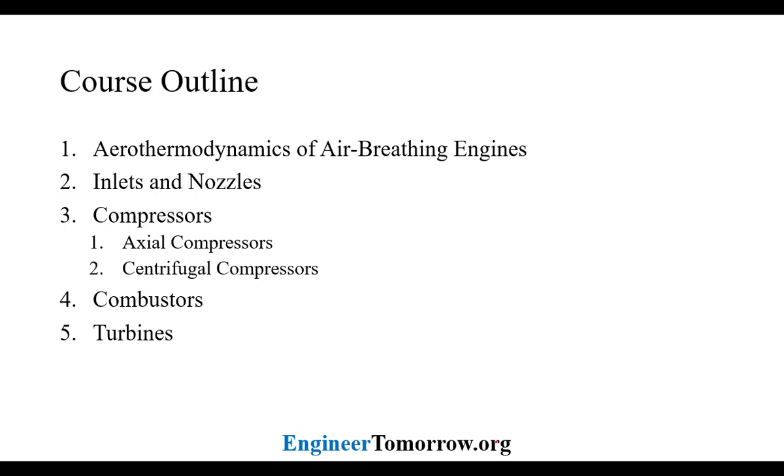Next, I'll talk about the turbine. So the turbine is what allows the compressor to turn. You start extracting some work, or energy, from the air going out of the combustor in order to power your compressor. And then some of the air you have to allow to get through, and that's how you create the propulsion.